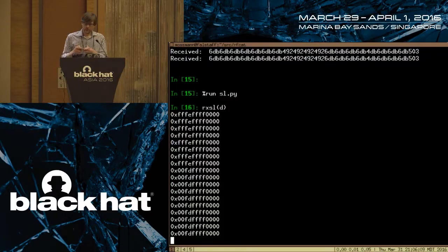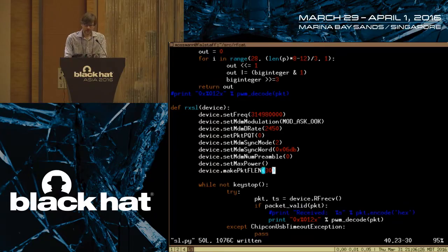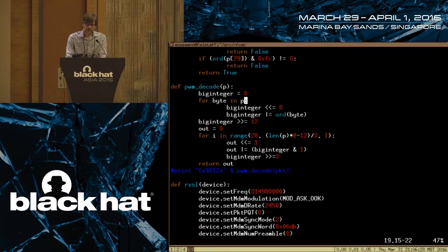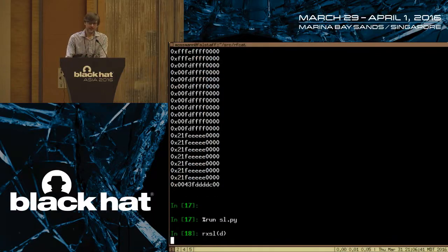What about 1, 1, 1, 1, lock? When I entered zeros, I got F's, and when I entered ones, I got E's, which tells me I probably have things inverted, if you think about that. F to E is like counting down, and 0 to 1 was counting up, which is what I pushed. So let me invert everything. If I go into my function where I'm concatenating bits together, and I XOR with 1, so I just flip that bit,